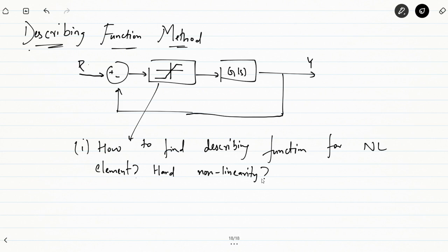Now we have done the phase plane analysis, but using the phase plane analysis we can only check the behavior of at most second order systems. We can go beyond second order systems by breaking them down into second order systems, but it becomes very complicated for phase plane analysis to describe such behavior. Also, phase plane analysis mostly only gives us a graphical representation of the system. It will not help us analytically solve or give us a function-based output response of the system, so that we can determine the behavior of the system for all values of time t.